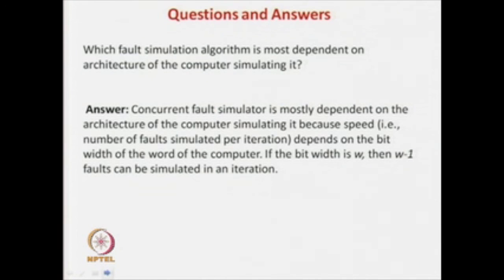The second question is, among all the 4 fault simulation algorithms which you have seen, serial, parallel, deductive and concurrent, which depends mainly on the computer architecture? Among them, only parallel fault simulation depends on architecture, because to each net you assign an array and the length of the array is processed in parallel. So, you have to think about bit parallelism. If your computer has 32-bit parallelism, you can have a maximum 32-bit array in all the inputs.